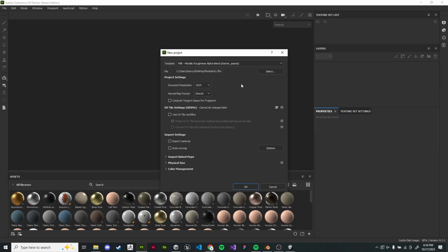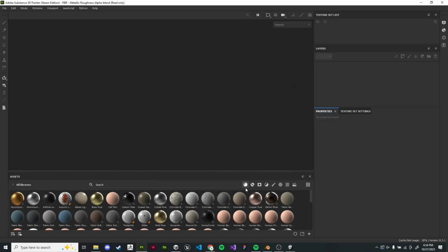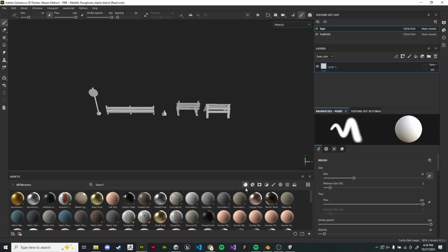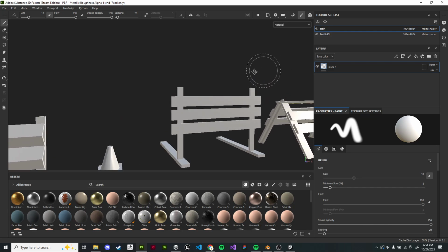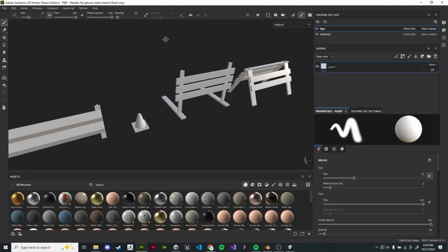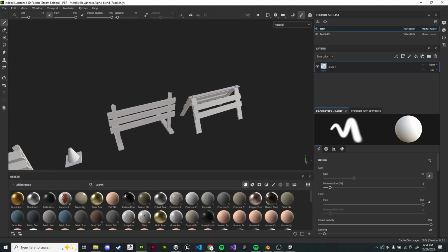All right? I'm gonna leave it at 1024 though, and then I'll make our signs probably 256 because we don't need too much detail. So PBR metallic roughness alpha, same as we've been doing, and then when we export, we'll use the Unity presets. So for now, OpenGL because we're doing Unity. Okay. So we have everything in our scene all at once, which is fantastic. We can double check that all of our normals are facing the right direction. So far, so good.